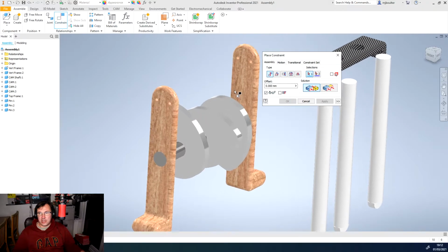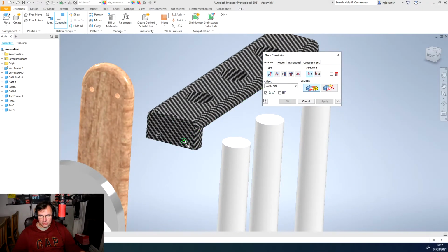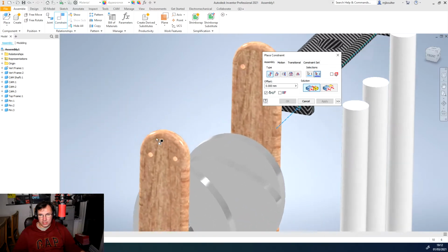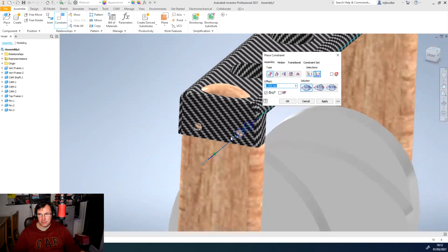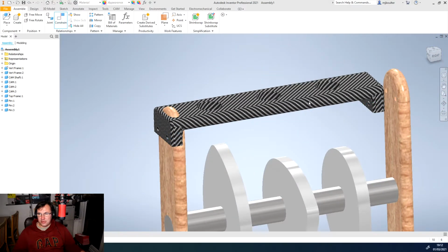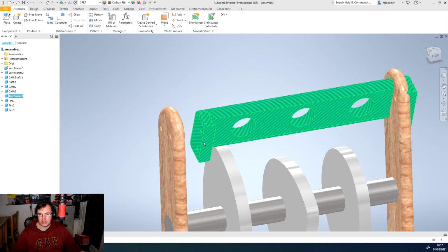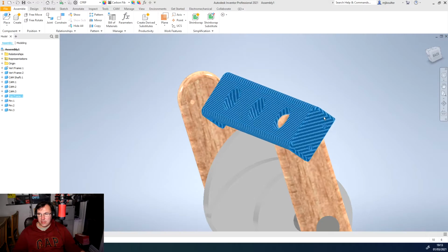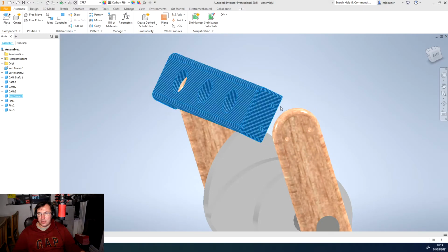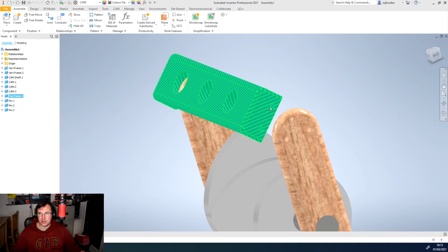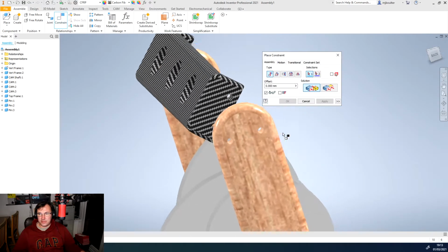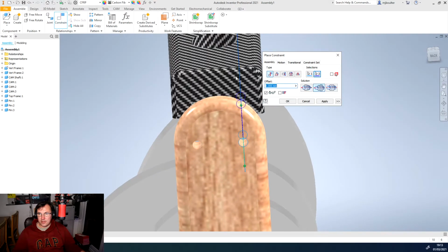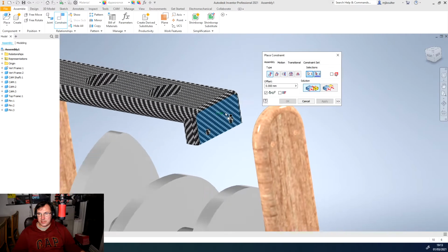So we'll constrain, again we're going to do an axis through the hole that's drilled in the top frame with the same hole in the vertical frame. And now we need to marry up the faces and then also stop it rotating by doing another axis on one of the opposite holes. So we'll do that first, and then we'll do the faces.